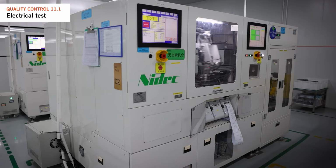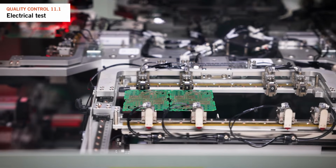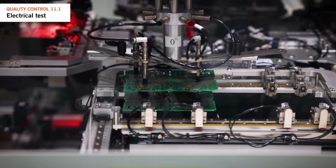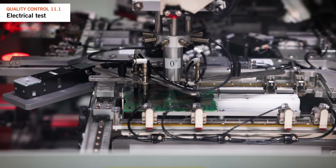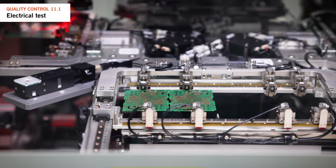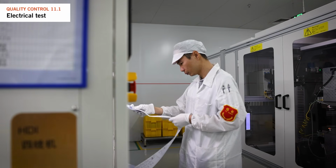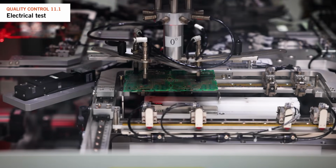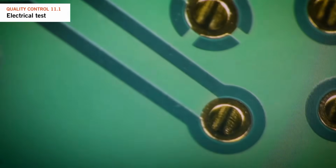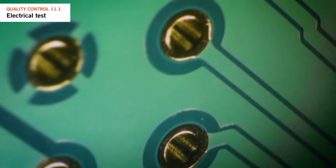An additional test is the 4-wire Kelvin test, focusing on checking net continuity and resistance. Hidden defects such as hole integrity can only be efficiently located by requiring a 4-wire Kelvin test. This is crucial for HDI structures, assessing the reliability of through-hole plating along with connections between blind via, microvia holes and their connected layers.